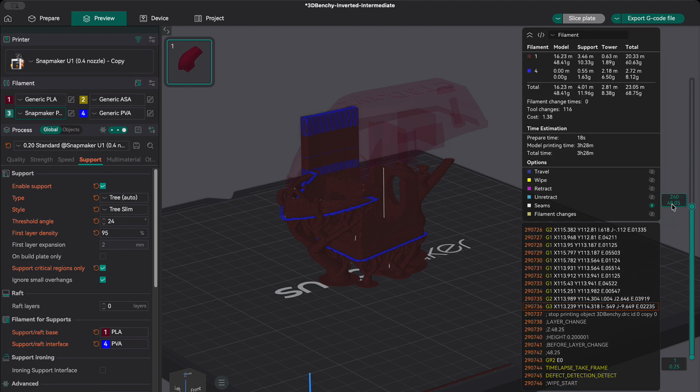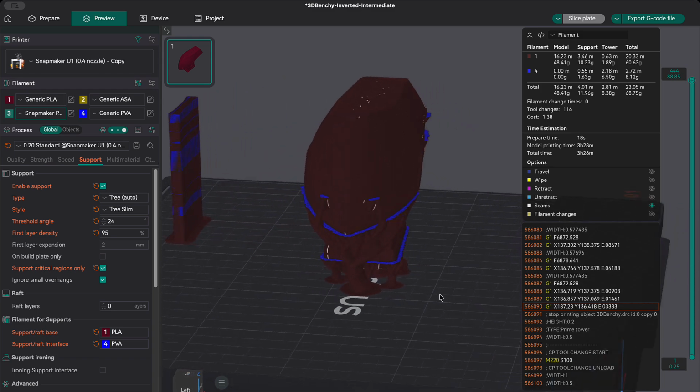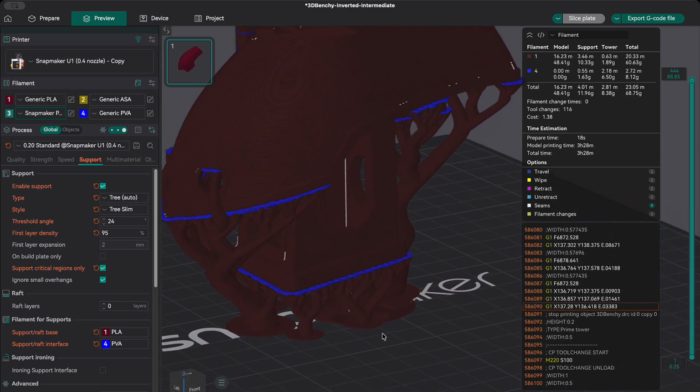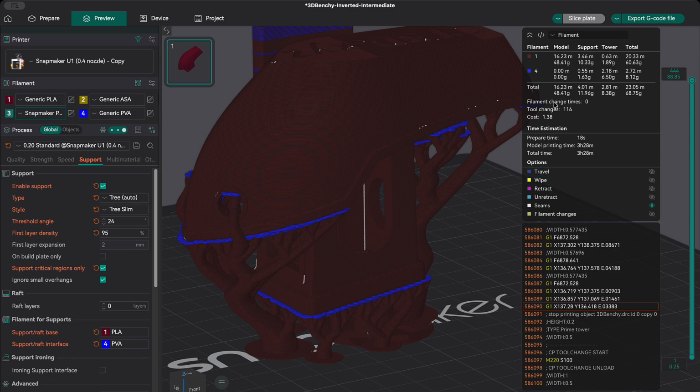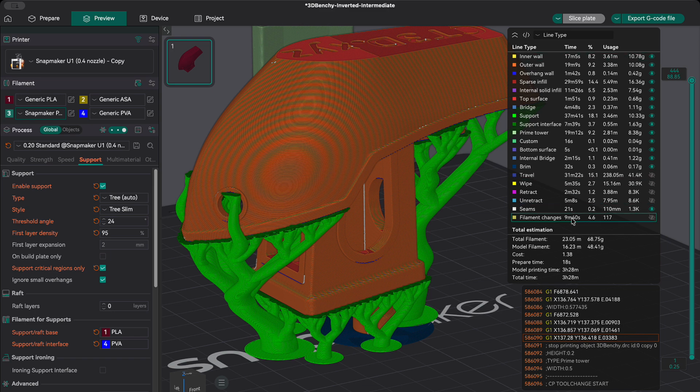Do not use a 0 gap blindly with normal same material supports, because the interface may fuse to the model. It should be used only with a tested soluble or deliberately non-bonding material combination. Check the filament preview carefully. Confirm that the model-facing interface uses the intended material, and review the number of filament changes, purge volume, prime tower,